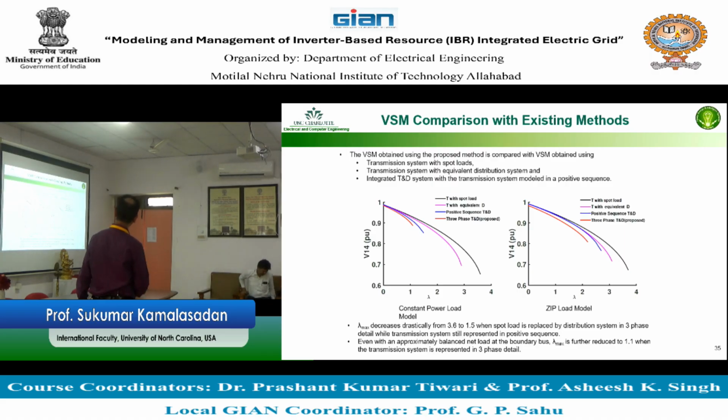And in some cases, with a constant power load. With the ZIP load, it even goes all the way to 2. With the ZIP load, we are saying that it is better now than the constant PQ load, which I think is good because you are reducing the power of the load based on the voltage. So all these trend lines you can get with the help of our simple power flow.